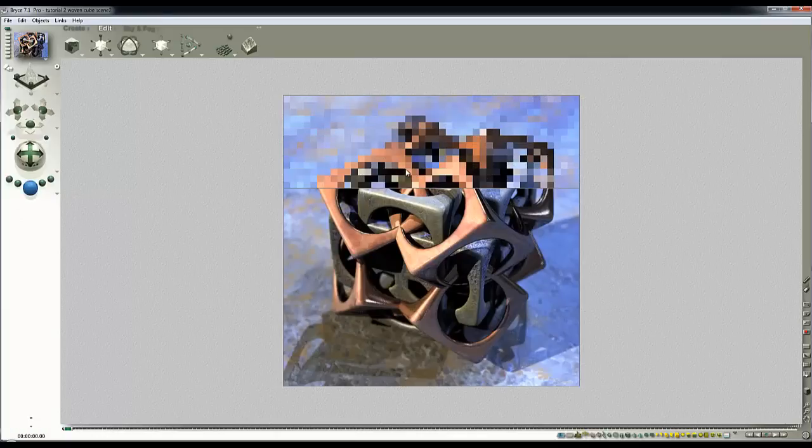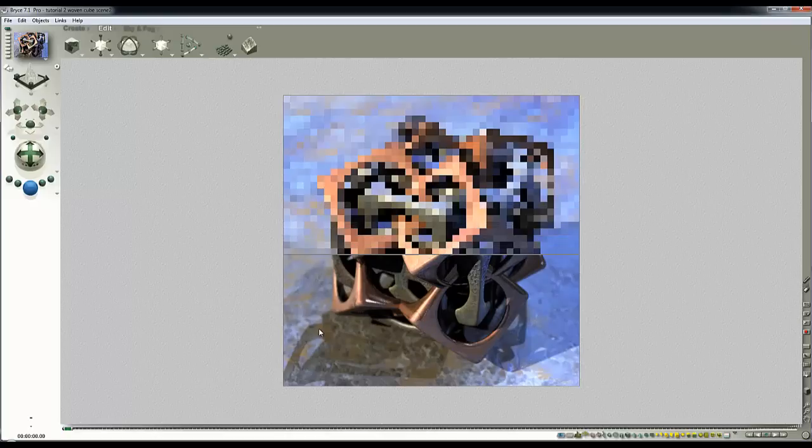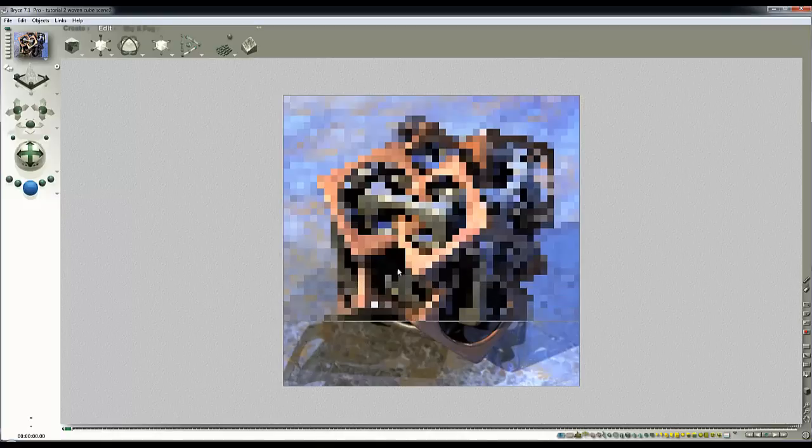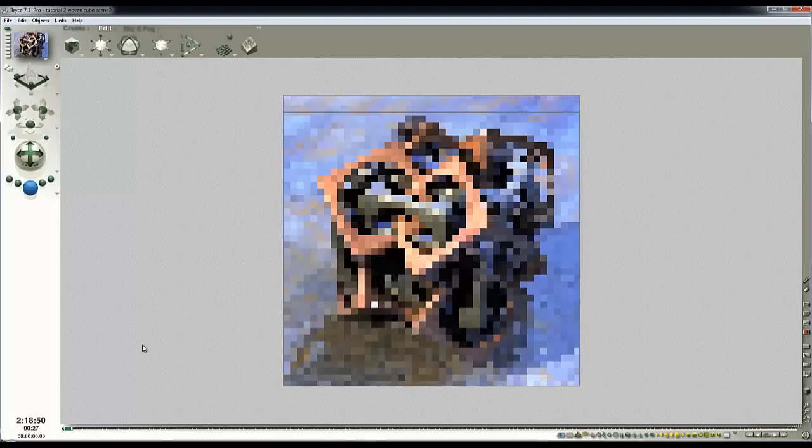So there's inter-reflections between the materials in the scene, and obviously the extra sampling to get the smoother depth of field is going to add considerably to the render time. What we'll do is we'll also plot render one of these corners just to look at the improvement. I'll reload the scene so you can have a comparison. First of all, let's find out how long it will take to render out at this. Okay, 2 hours 18. Right, so File, revert to saved, revert.